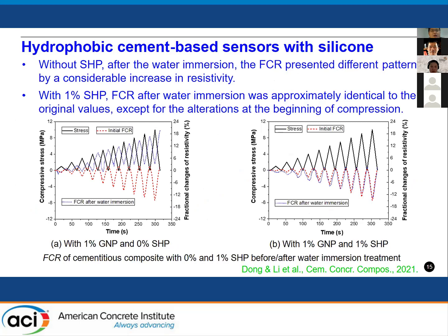All right, so now let's look at the fractional change of the resistivity of the hydrophobic cement-based sensors with or without SHP, after or before water immersion.